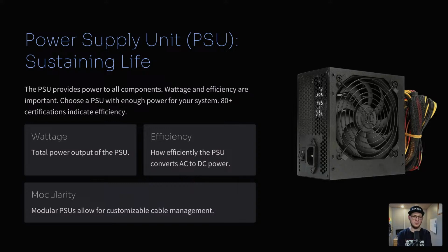It also comes with different levels of efficiency. So you'll see things like 80 plus copper, 80 plus gold, 80 plus platinum, and so forth. That's just the efficiency level. So when it's running at 100% power, how efficient is that? If you have a 1,000 watt power supply, which is pretty big, unless you're running a higher end setup, unless you have that 5090 for an example, you're probably not running over 1,000 watts. But if you are maxing out at 100% capacity on your power supply, if you have the 80 plus platinum for an example, then only 5 to 10% of that power is not being used. It's going to waste. You're always going to have some of that power go to waste, but that's just how efficient it is. And then also, it mentions here that modular section as well.